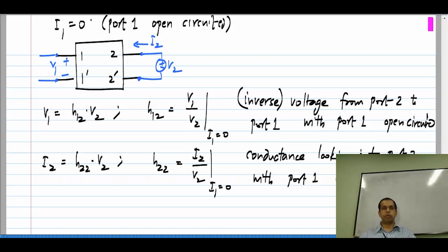To describe the small signal model of the bipolar junction transistor, these H parameters were widely used, but actually the current style is to use Y parameters, the admittance parameters for both the bipolar transistor and the MOS transistor. Okay. So, you will see those things when you take a course on active circuits, that is amplifiers using bipolar transistors and MOS transistors. Okay.